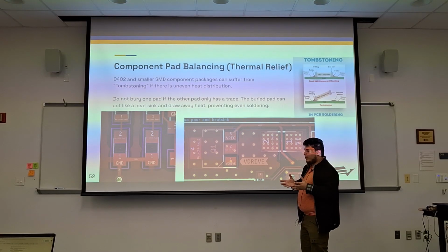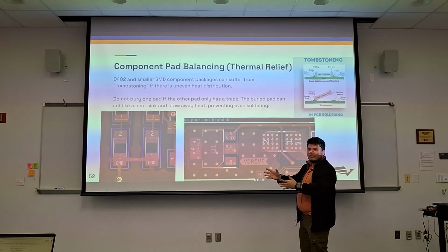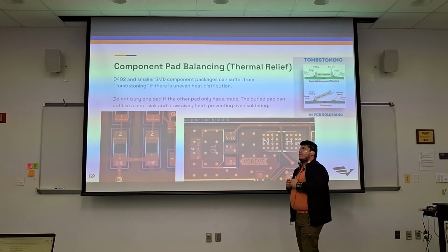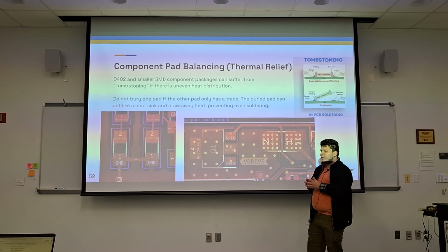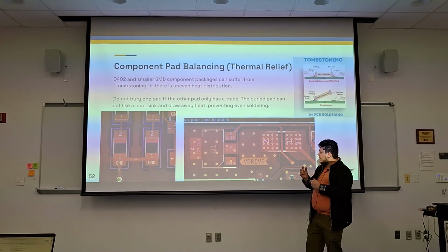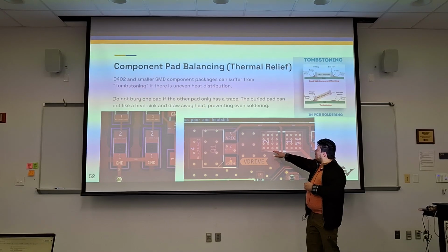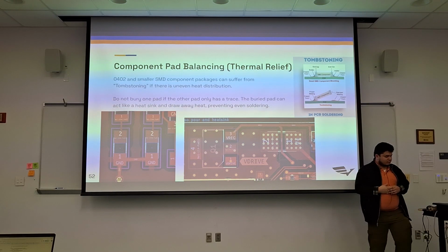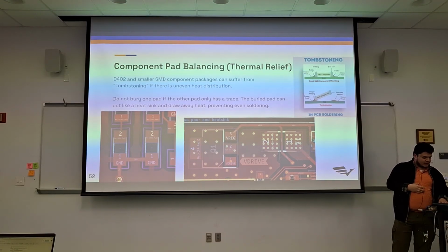But save yourself the rework and just thermally relieve your components, especially if they are a 0402 package or smaller. Those are the most problematic. So 0402 components, tiny little SMD components or smaller, have this issue. So never, ever flood those pins if they're that tiny. This is a bigger package, so less problematic, but still a risk. I didn't learn this one until I was in industry.